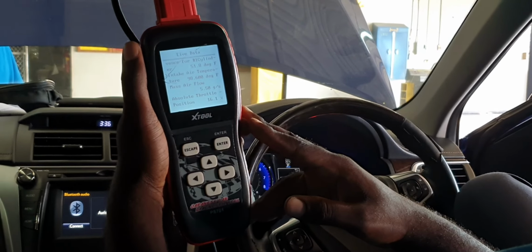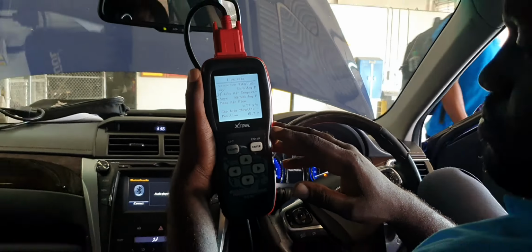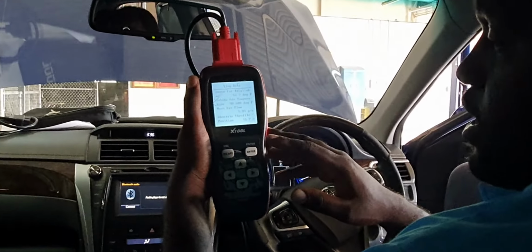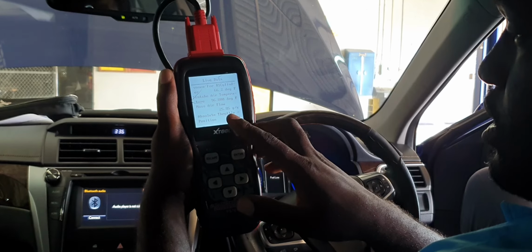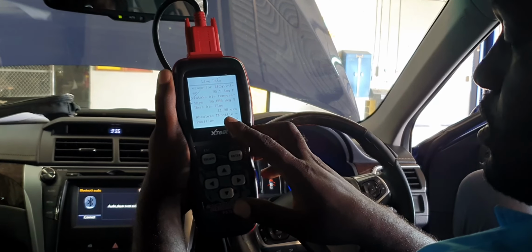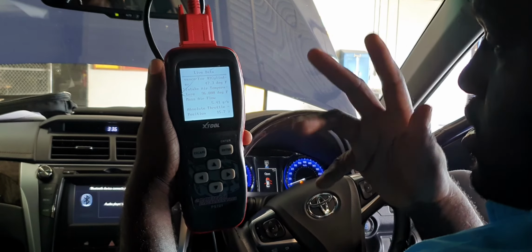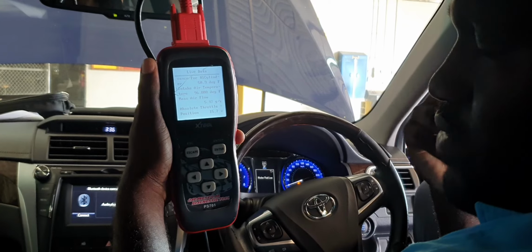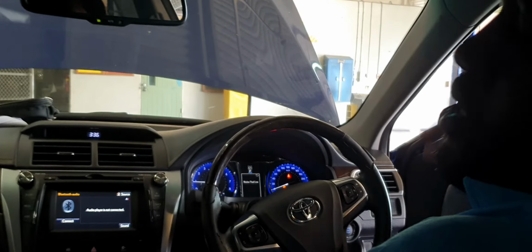Alright, so there it is. So there we have 9.8 and we have 6.8. And if we should accelerate, we should see some difference in reading in our airflow meter. Alright, and this is GS, this is not voltage. So technically this is just the basics of our powertrain management system. In the next class I'll be giving you details of how the sensors and actuators, we can actually test them and evaluate them. And that's it. Introduction of powertrain management.